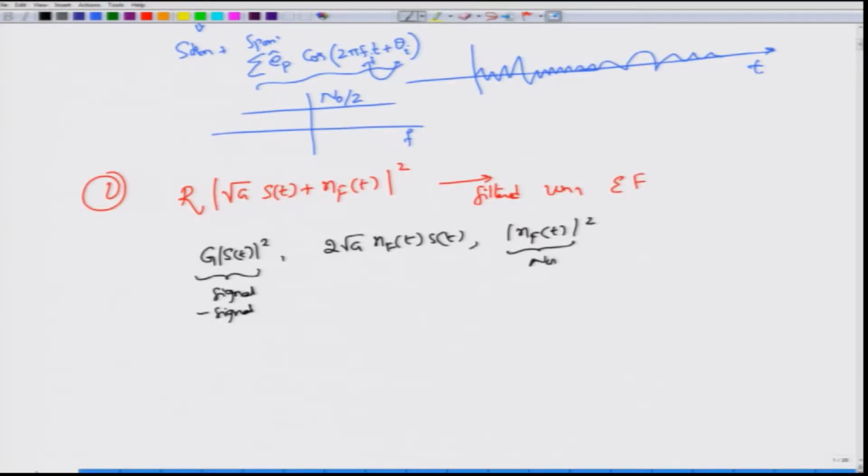This is just the noise, and the noise source for us is the amplified spontaneous emission source, sometimes denoted by the spontaneous emission noise SP. So, this term is the spontaneous emission noise talking to itself, or beating with itself. This is called the spontaneous-spontaneous beating term. Finally, you have a cross coupling between signal and spontaneous noise, which is called signal-spontaneous noise beating. Our objective is to look at all these terms individually and then find out the noise power and the signal power, so that it allows us to write down the signal to noise ratio of this amplifier.